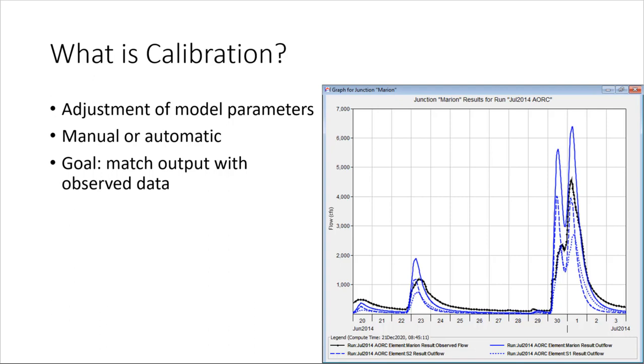Usually, we determine if our model matches reality by comparing model output for observed past events and seeing if key results match. We may consider whether the simulation of streamflow at locations where we have flow observations match reasonably well. We may also compare observations for other hydrologic processes, such as snowmelt and accumulation and evapotranspiration. There are some so-called automated tools for performing calibration, but the most reliable way to produce a calibrated model with reasonable parameters is to change the parameters yourself until the model results match observed data.